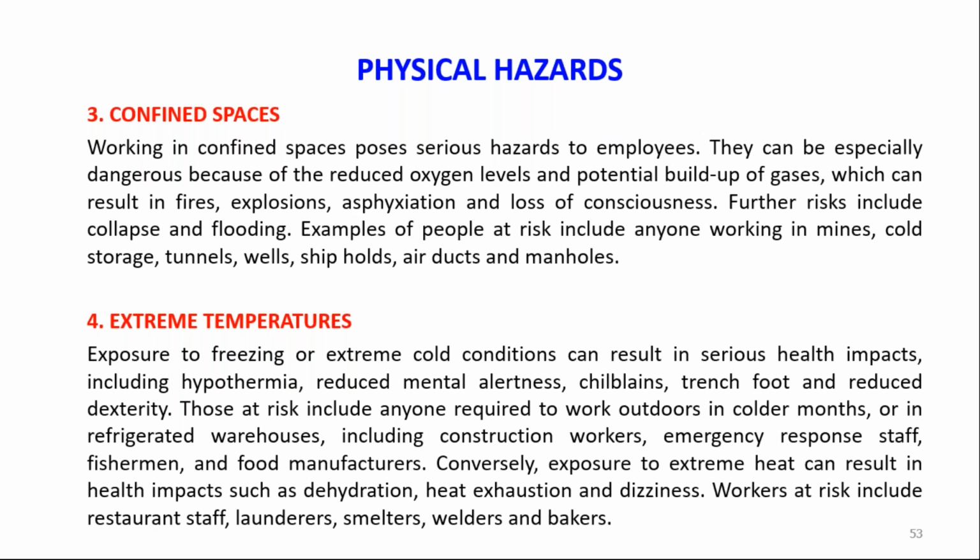Other than the oxygen level, some cases are fire, explosion, asphyxiation, or loss of consciousness, which may happen due to low oxygen levels, because our body requires at least 21% oxygen at normal conditions. If the oxygen level reaches less than 19%, then depending on your body, the person may suffer suffocation, and in a severe case may lose consciousness.